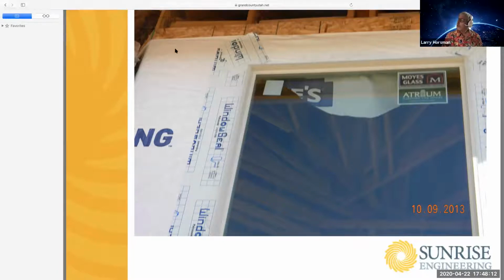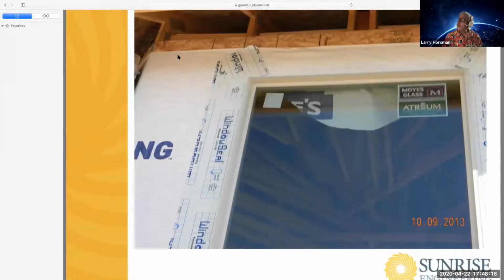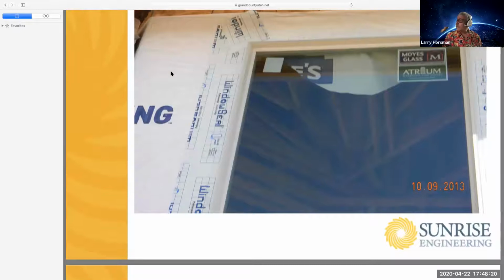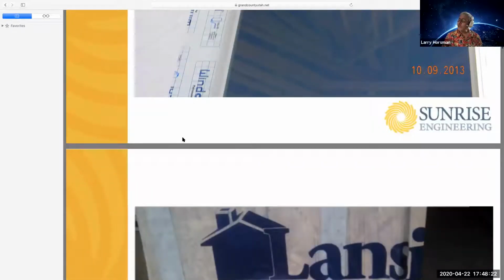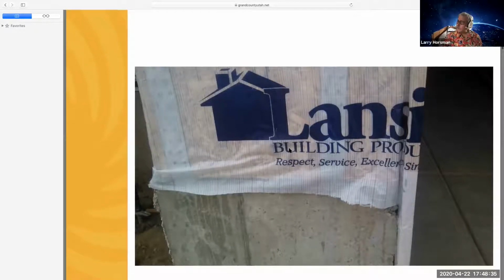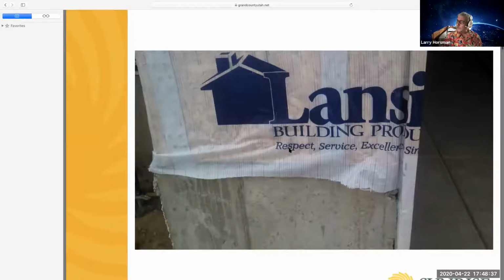And I know they had to change some of the house wraps because originally the stucco was sticking to the house wrap and trapping the water. So this stuff you can kind of see, it looks like it's set up to have some little drainage channels vertically in the house wrap, and that's so the water doesn't get trapped between the wrap and the stucco, which it'll sometimes stick to.